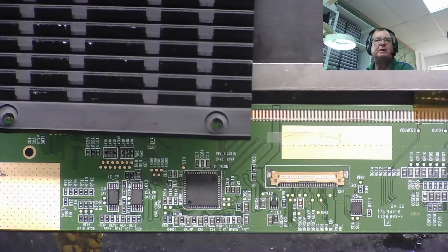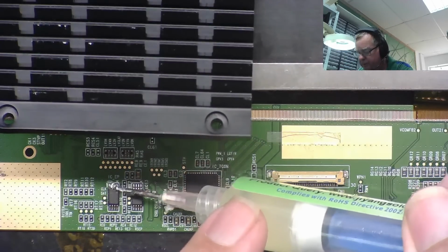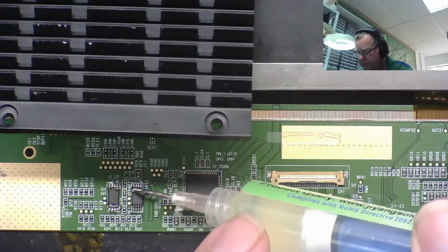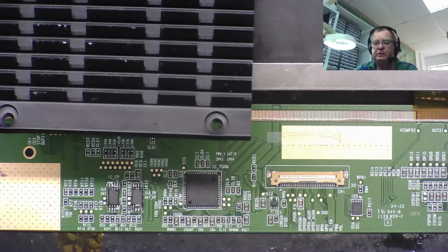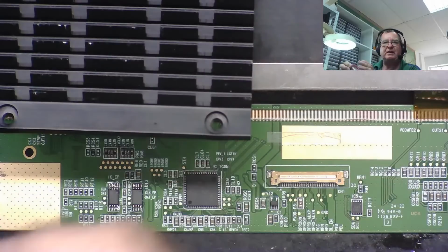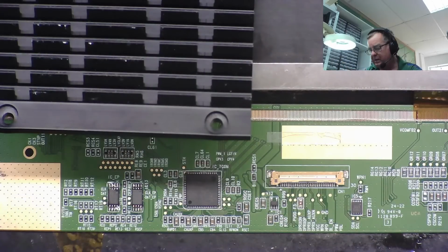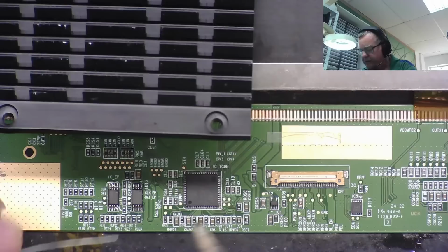So yes, soldering iron is on. Let it warm up a little bit. Flux, of course. So let's put some flux on these. That bleep, that was the soldering iron just on. A bit of flux on these EPROMs. And I'm going to get some solder on both ends. I don't really care if I bridge them. In fact, if I bridge them, it'll probably come off easier. So I'm not too worried about bridging the legs together at all. I can clean them up afterwards.